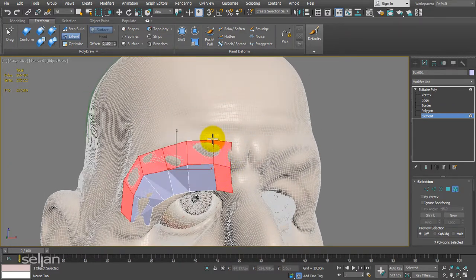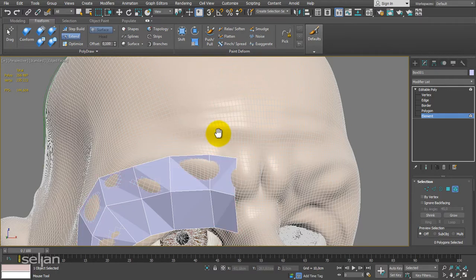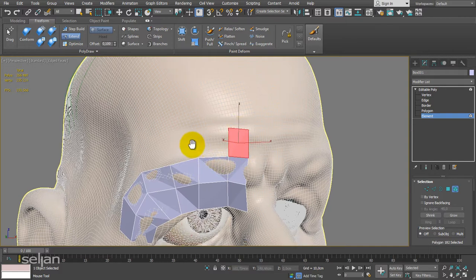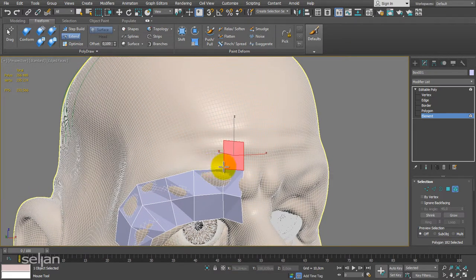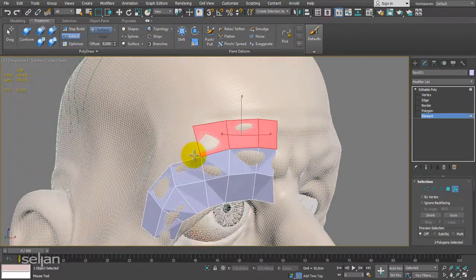If I want to move forward, what I can do, oh, not this one, I can delete this one, because we have the control hotkey. So if you press control, now you can delete a polygon, and again, shift and drag will create an extrusion polygon, and from a simple vertex you can start the extend if you don't use any other hotkeys.